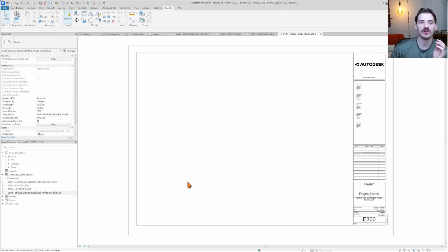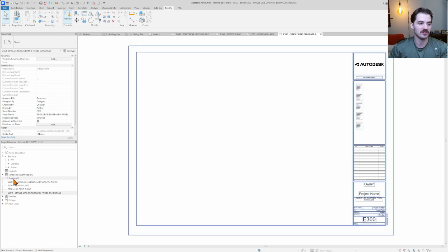It's really important to remember, if you're familiar with AutoCAD, this is basically the same thing in Revit, where we're in paper space, as you would call it in AutoCAD, and in views, we would be in model space. But if you're not familiar with AutoCAD, this is a really key thing to understand about these programs, is that we're delivering a set of construction documents, right? Which used to be pieces of paper that the contractor would look through on the site. Now it's almost always PDFs, right? Sometimes they'll print them out, but what we're doing is creating a document, a PDF of sheets that show all of the information that we need to show, right? And so that's all that this is in Revit, it's a sheet.